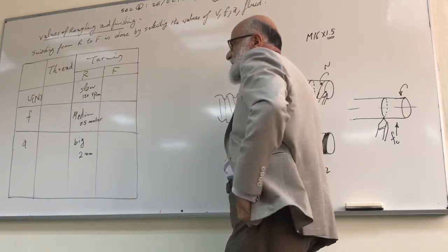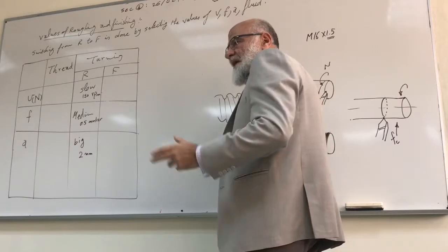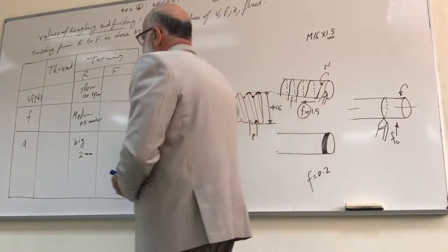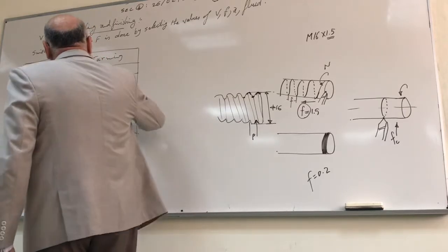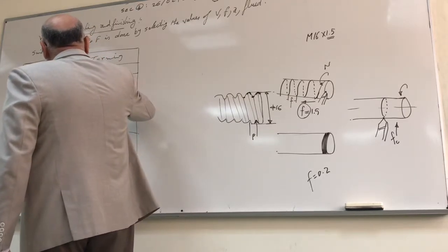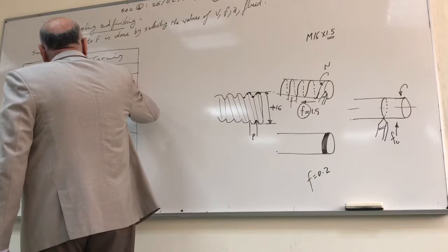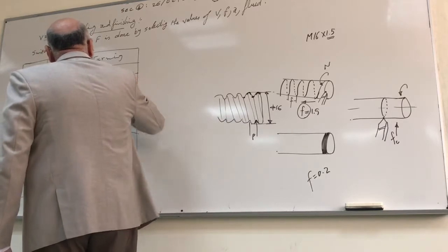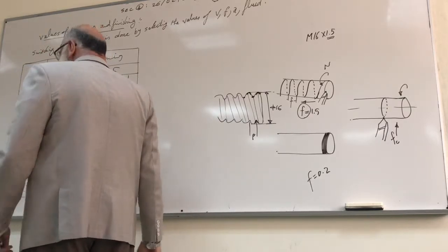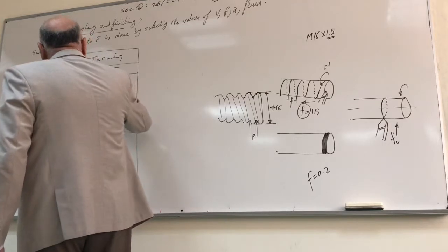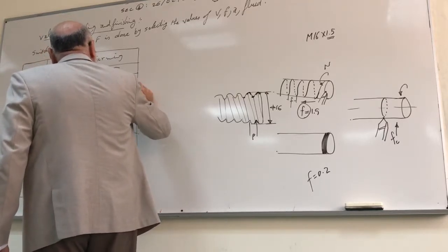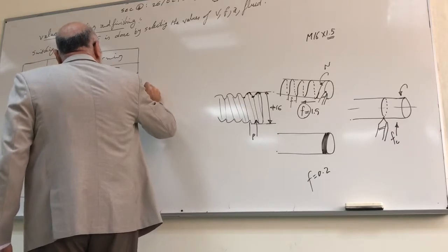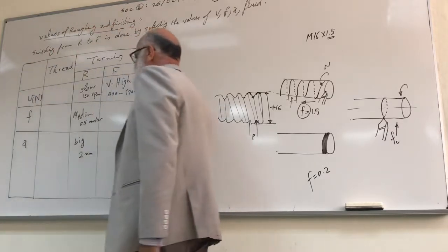About the finishing, it is the opposite. In fact, we take here high speed. We take very high speed, which is revolutions per minute. Meaning start from 400 up to 1200 revolutions per minute for finishing.